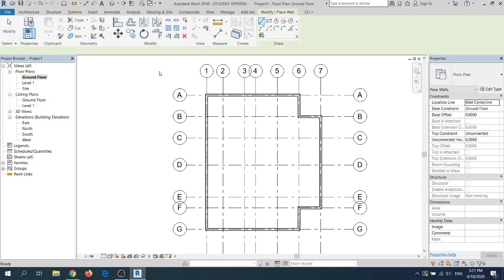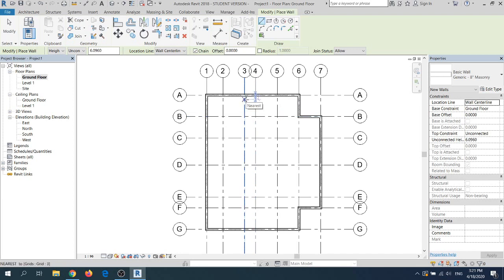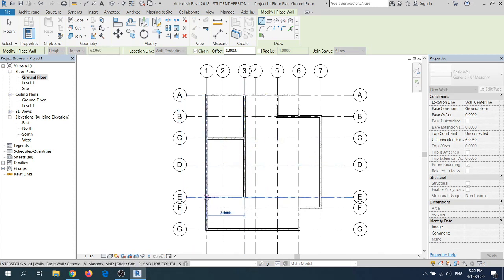Click the architecture wall again to select the wall that you want, to finish all the internal partitions you want. So for example, this is a factory drawing I would like to draw, so definitely you must have a small toilet, so I make a partition for a toilet. If you want to have your administrative room, motor rooms, aircon rooms, etc., you can draw them accordingly. So I will just do a partition here for meeting rooms or even an administrative room.